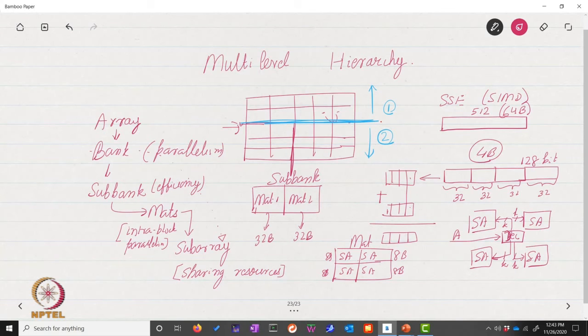So if you think about it, this is a complex hierarchy and we have a few more optimization terms. So these things CACTI 6 hardwires but need not be hardwired. So one optimization term is the number of banks. So this would of course require architectural simulations. The number of sub-banks within a bank, right? Number of mats within a sub-bank, right? And the number of subarrays within a mat, I mean that's not an optimization term because the number of subarrays is known in advance. It is essentially NDWL times NDBL. Alright?